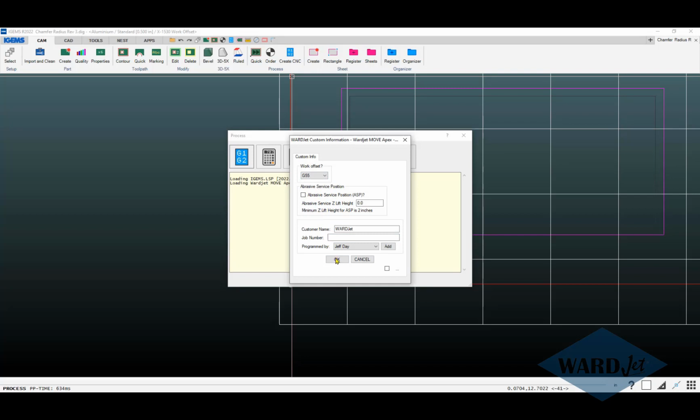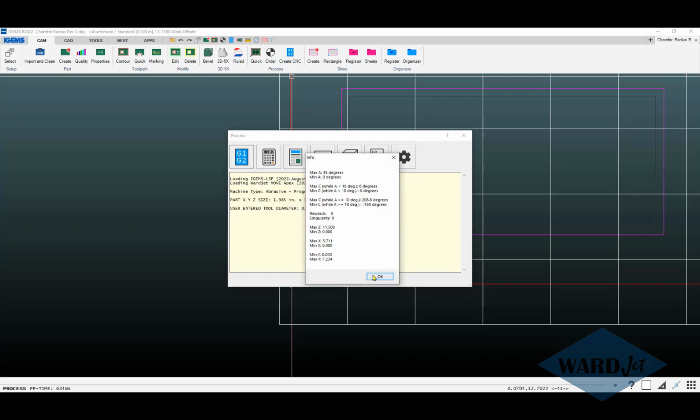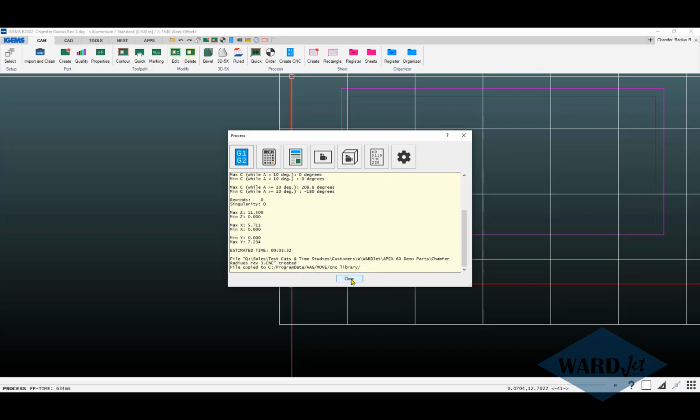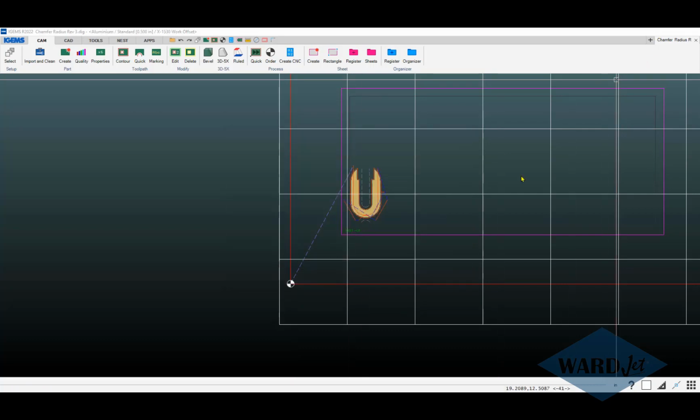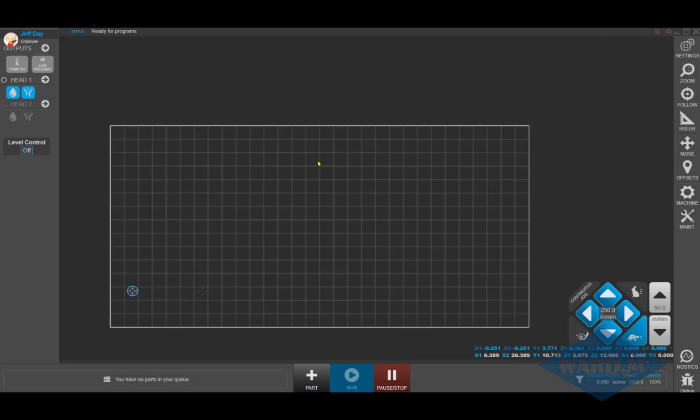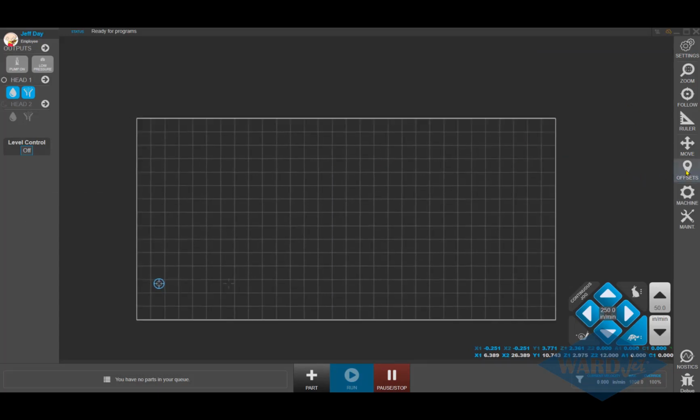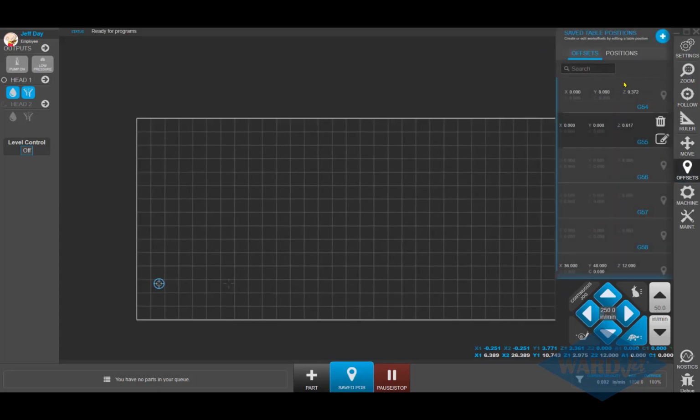And with that, in the controller, it will look at our saved G55 position. So here in the controller, up here in this offsets area, we can have G54 through G59 used, and for G55 we have set X0, Y0, and then the Z is set so that we're going to be 1/8 of an inch off the top of our 1/2-inch material with this value here.